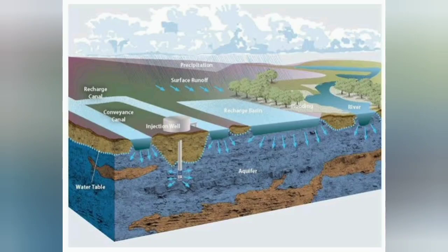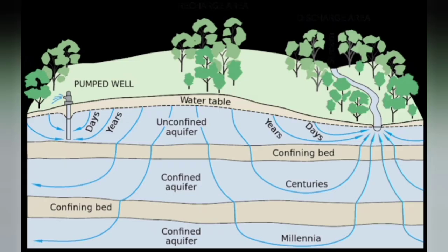Negative or non-productive zones of low hydraulic conductivity in unsaturated and saturated zones. Vertical hydraulic conductivity discontinuities such as dike and fault zones, moisture movement and infiltration capacity of the unsaturated zone, direction of groundwater flow under natural or artificial recharge process, salinity ingress, and depth salinity changes in the aquifers due to varied abstraction or recharge.